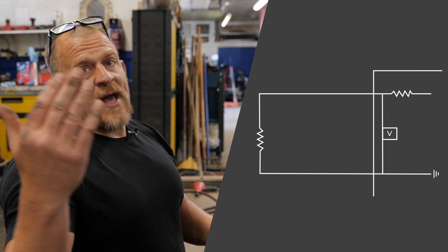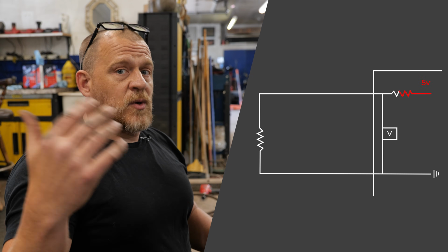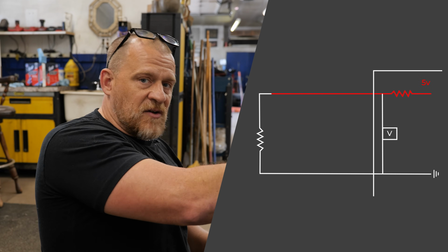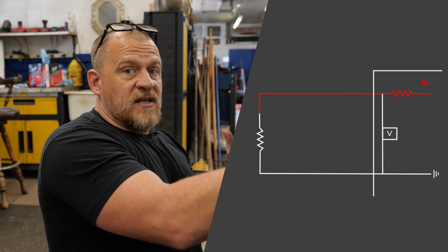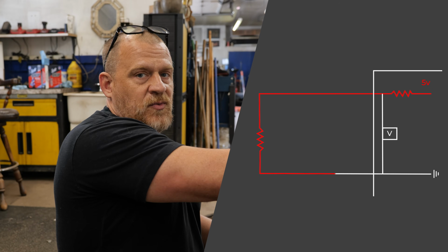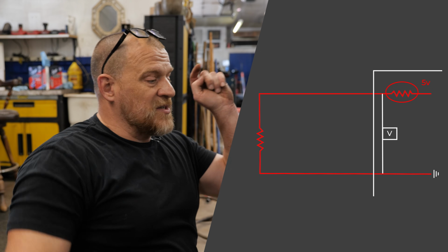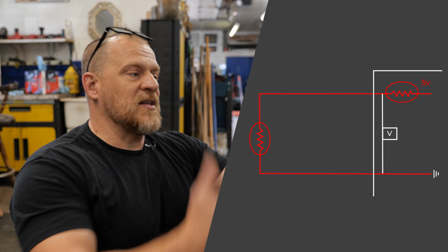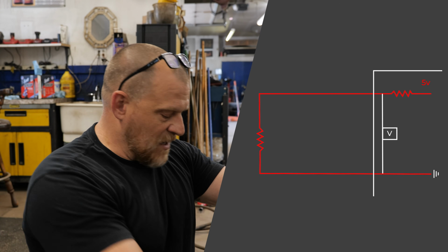This would be one where we have 5 volts as the source that goes through a resistor in the module before it comes out to here. And then the other side is dropping across the external resistor. So resistor in the computer, resistor is the sensor. And that's why we see that drop from 4.7 down to 0.78.